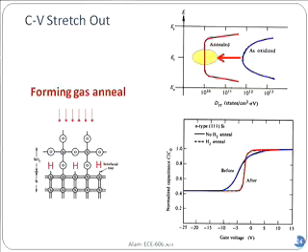Because in all the capacitances that we had been looking into, accumulation was at negative gate voltage because the substrate was p-type. Now, this particular diagram I have taken from the book. In that case, the substrate is n-type. If it is n-type, then you realize that all the voltage polarities required to see accumulation, depletion and inversion will get reversed.